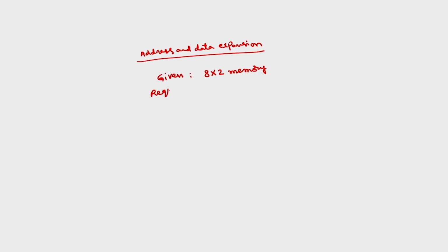Address and data expansion: suppose you are given 8 by 2 memory and the required memory is 32 by 8.